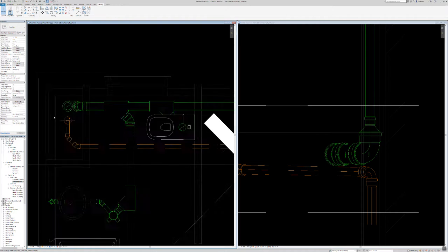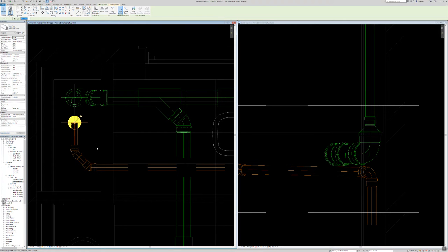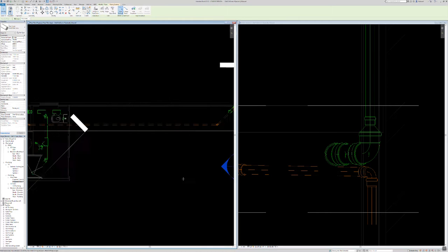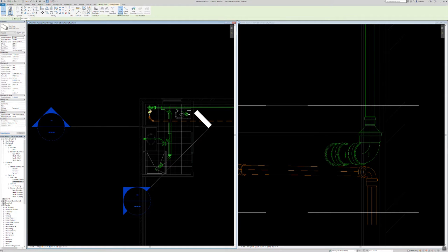Now, like I said, sometimes you'll have an offset way over here, and they will then show up. There are two ways you can handle it. You can set your view range to be 50 mil below the slab, which gives you that 50 mil lenience.